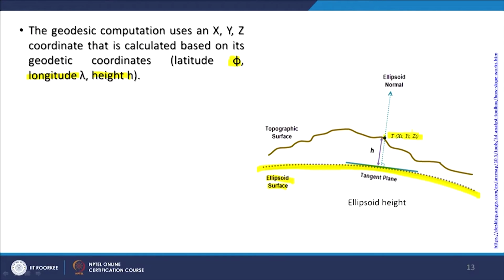But whether that height is perpendicular to our tangent plane, which is just touching this ellipsoid surface, or not. If it is coming from the earth center, then definitely it would be the ellipsoid normal, otherwise not. So variations may come, which is why in GNSS you get variations. You expect something but you may not get the accurate elevation value.